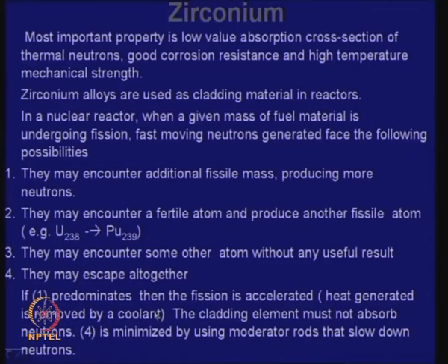This generates a lot of heat, because every fission reaction means generation of neutrons, thermal neutrons. Also, the fissile material is split into two equal masses which go in opposite directions with high energies, and there is a lot of heat generated by that process. The material in a cladding material like zirconium alloy stands that heat, but at the same time we have to take out that heat, because that is the energy which you are going to use from a nuclear reactor. So, that is removed by a coolant.